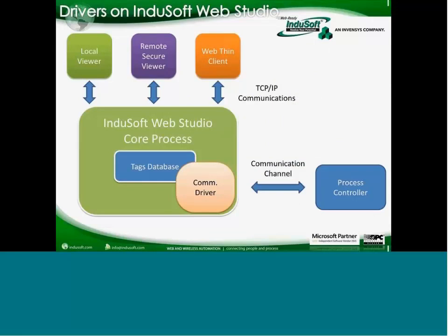Okay, so a little bit about the architecture, where the driver goes on InduSoft Web Studio. So first we have the InduSoft Web Studio core process. And the heart of the product is actually the tags database. So the tags database receives the data from, let's say, the driver, the OPC, or any other task that may change the value of one tag. It processes and sends the data out to all the other tasks.